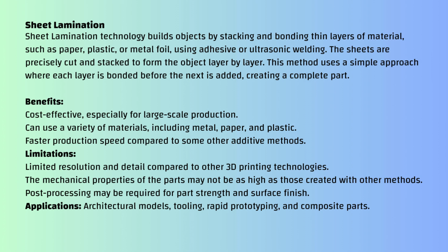In ultrasonic additive manufacturing, UAM, thin metal sheets are ultrasonically welded together. This method is relatively fast and low cost, and UAM enables embedding of sensors or electronics between layers. However, it has limited resolution and is mainly suited for visual models or specific research applications.